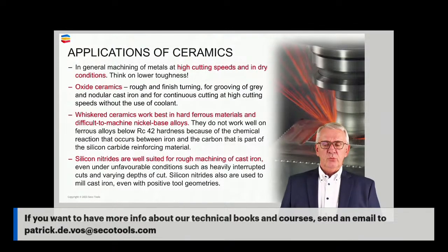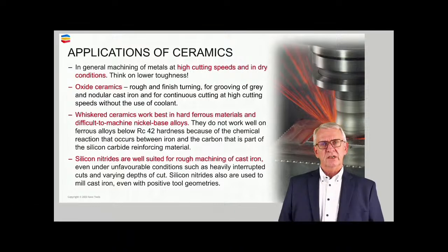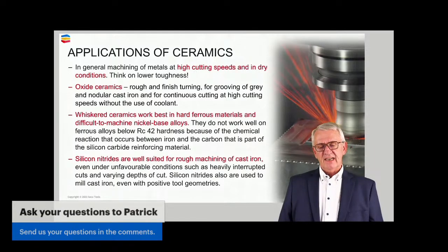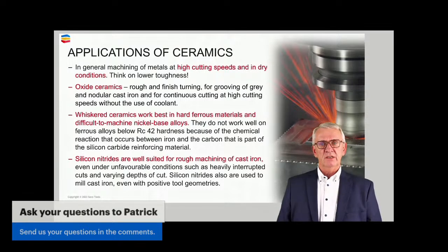Ceramics, a little bit the black sheep in the family, or am I exaggerating now? I don't know, but ceramics is a big branch in the meantime in the family of advanced cutting materials. Remember, you have big groups there: the white ceramics, the black ceramics, the whisker reinforced ceramics, the sialons, the silicon nitride ceramics. If you look at the total picture, yeah, they serve a big domain of applications, ceramics.